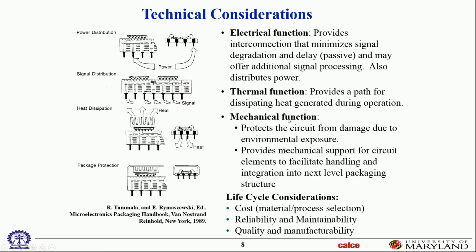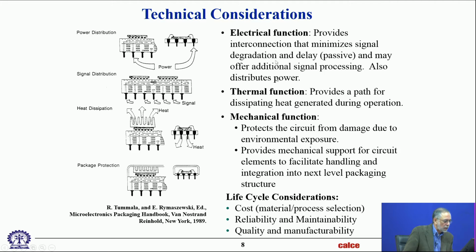Okay, and this is just putting in letters what I've been saying in words all the time: now you have to worry about electrical, thermal, other mechanical considerations like mechanical stresses, and other life cycle considerations. Well, what's missing here is chemical, right? Chemical plays a big role. Harsh chemicals come from the environment. Harsh chemicals come in the product itself as part of the manufacturing and processing chemicals. All of those eventually cause aging of the system.